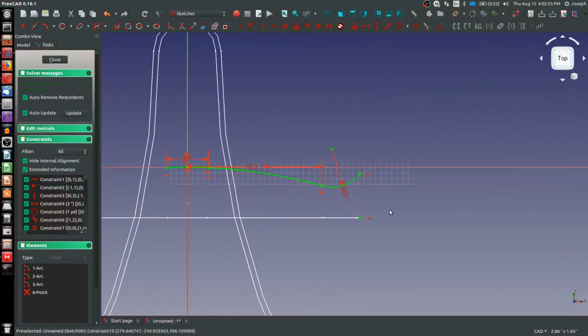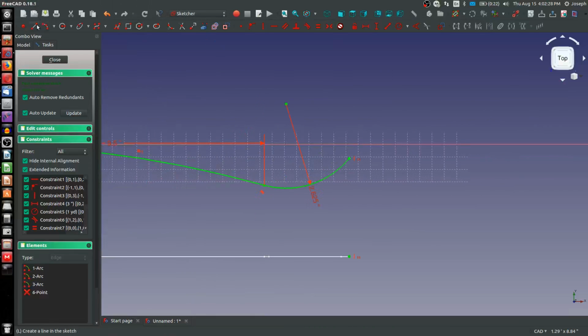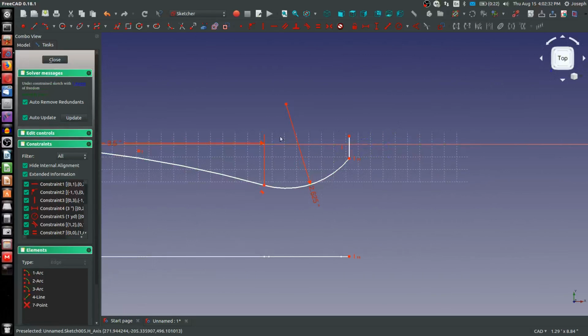From here, I could make these edges a little bit thicker. Let's say our design intent is to have a little bit thicker than normal here, so that you have a little bit more reinforcement if you were to lean back in the chair. So we'll make that vertical instead of normal, and that adds a little material buildup. That makes it much harder to injection mold, but it still should be relatively interesting. So it should relatively work.